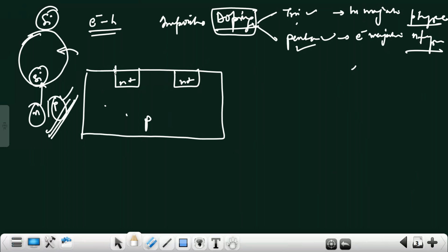Now what you have to do? You have to etch this part. Etch means there is a process called etching in fabrication. So you have to dig out this part and then you add the impurities such that you get N-type material here. Now you also need to add silicon dioxide, right? And then on top of it, polysilicon. Now these are what? Metal connects. So we don't know which one is source. Let's say we'll add source, drain, and this is gate. Now this will be connected to metal layers, right?